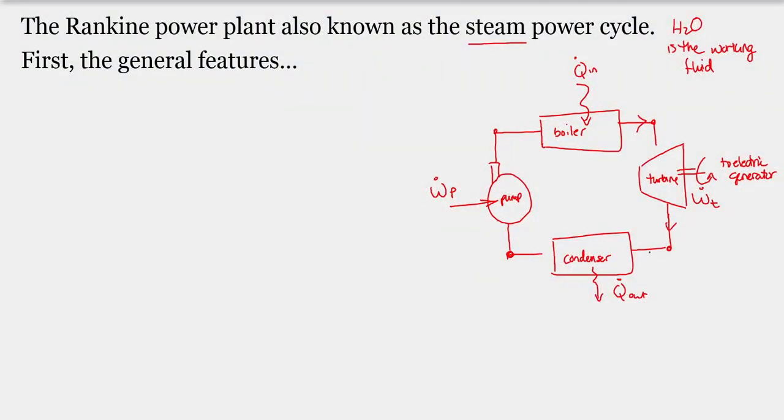Okay. So this portion requires that we have some sort of cooling pond or some cooling lake. Notice that at all times I've considered this a closed loop system. So we're not at the point where we would consider including makeup air. So this is entirely closed. The working fluid does not leave this system. So this cooling pond, what we have is essentially a heat exchanger down here where this working fluid does not mix with the fluid in the cooling pond. So I want to make sure that that's clear.